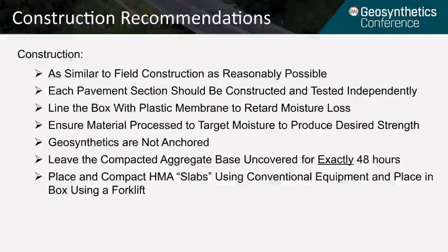Line the box with plastic membrane to retard moisture loss. Materials should be processed to the target moisture content necessary to produce the desired material strength for the experiment. In general, the geosynthetics are not anchored, although some experiments have anchored the geosynthetics or folded them up the sides. This is inconsistent with best practices.